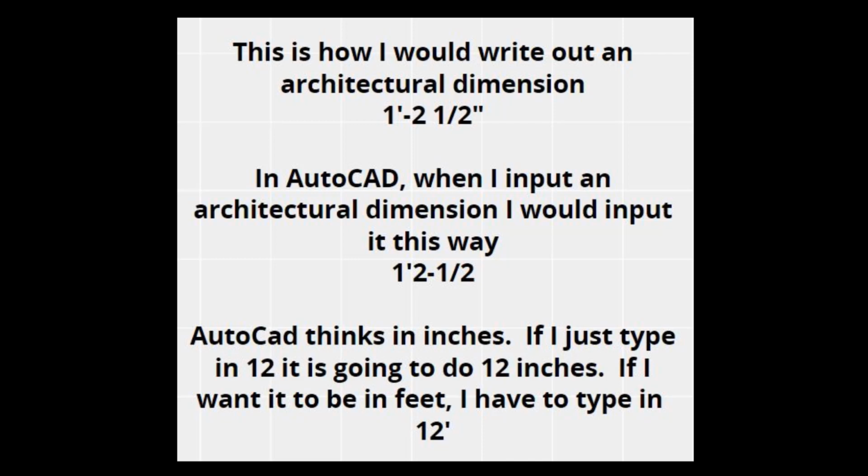But then I don't put the dash. I go directly to the full inch. So I do 1, the foot mark, 2, and then once I finish 2, I have to tell it, okay, now I'm going to give you the partial inch. So then I put the dash in and my 1/2. So you basically reverse the 2 and the dash, and there's no space. So that's very, very important. If you try to put it in like you would typically write it, it's just going to keep not doing it for you and asking you for the point over and over and over again.